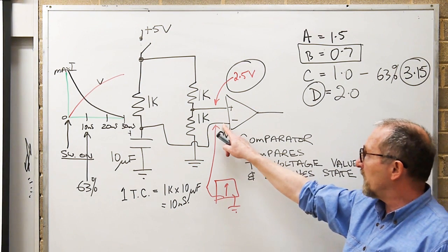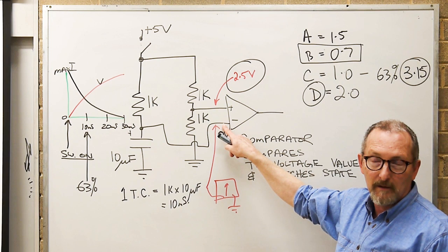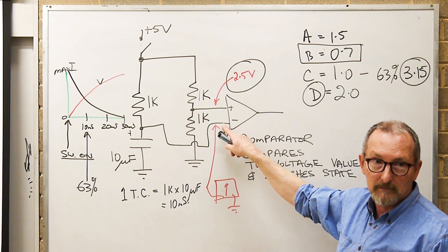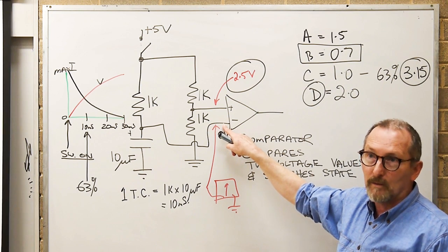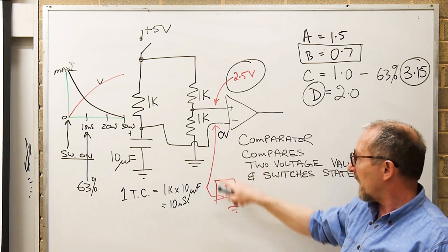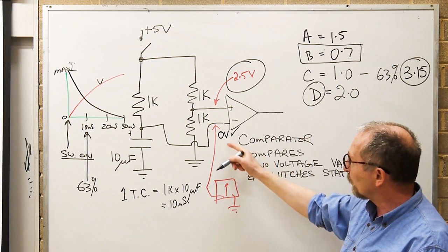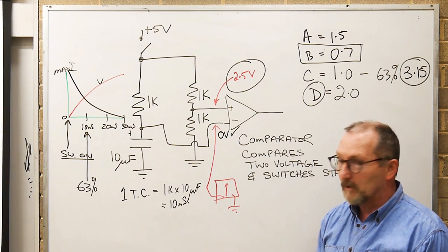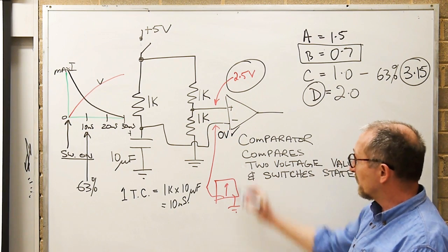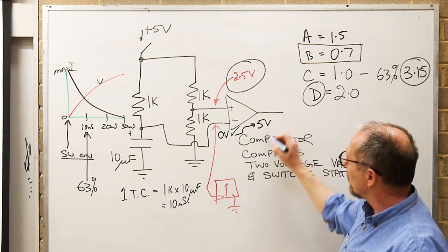Oh, what's the voltage here after 5 time constants? So that they realise there's a transition on that leg. So it goes from 0 to something else. Well, yeah, it starts at 0 volts. We said it starts at 0. But what does it reach after 5 time constants? Yeah, that's a good question. Lachlan? 5 volts. Has to be 5 volts. 0 to 5 volts.